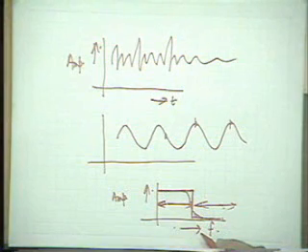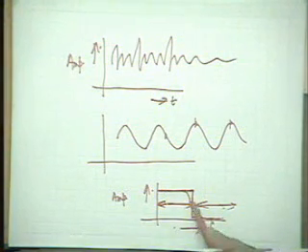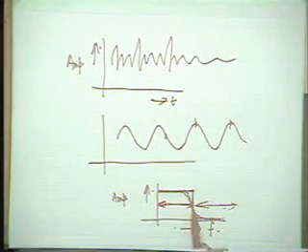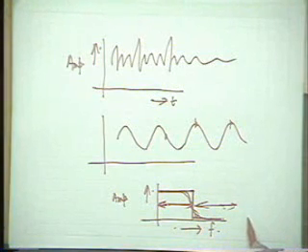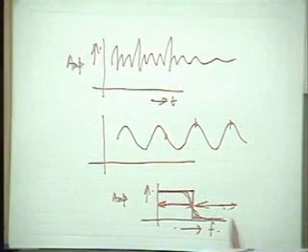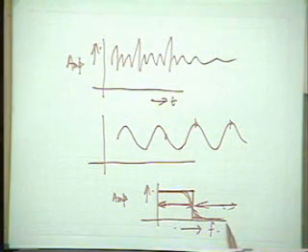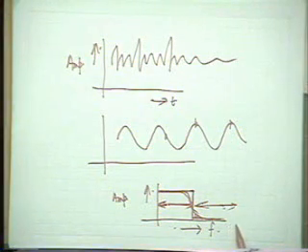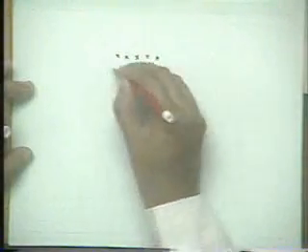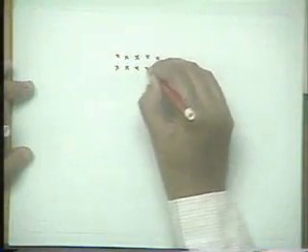So, this is a typical non-ideal filtering, but this is a low pass filter because as we go to higher and higher frequencies, the higher frequency components are being suppressed more and more by this kind of filter. Now, in the case of interpolation, what we are doing is something like this. Supposing we have been given the image data at the integer grid points.